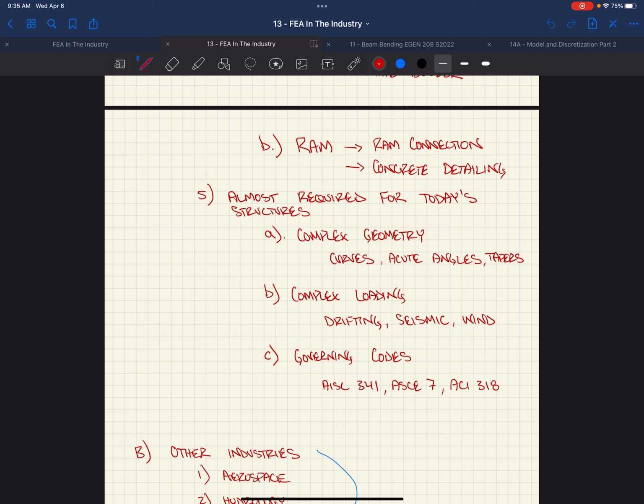And before that, I wish I was there before that, because the black book was the first time that you really had to do anything. Before that, it was the Wild West. I looked at old drawings we did at Morrison Maierle for houses up in the Yellowstone Club that use a lot of moment frames because they got big windows and stuff, right? And they would have called it a special moment frame. In no way in hell is it a special moment frame by today's standards, right?